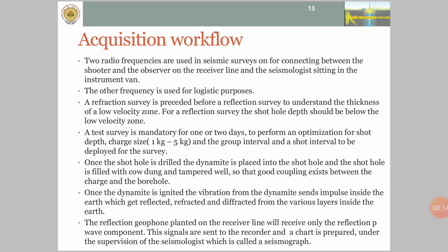A refraction survey is preceded before a reflection survey, which I told you before, in order to understand the thickness of the low velocity zone. For a reflection survey, the shot hole depth should be below the low velocity zone. This should be kept in mind. In a reflection survey, when we fill the shot hole with dynamite, that filling and blasting should take place on the same day, because we cannot fill these shot holes the day before and then blast the next day.